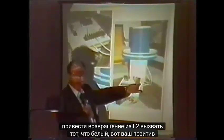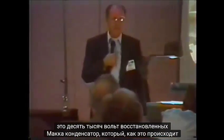It's working between the blue one here, which is the negative lead coming back from the L2 coil. The one that's white here is your positive lead going out. So between those two, in relation to your other things, you've got this 10,000 volt reconstituted mica capacitor.